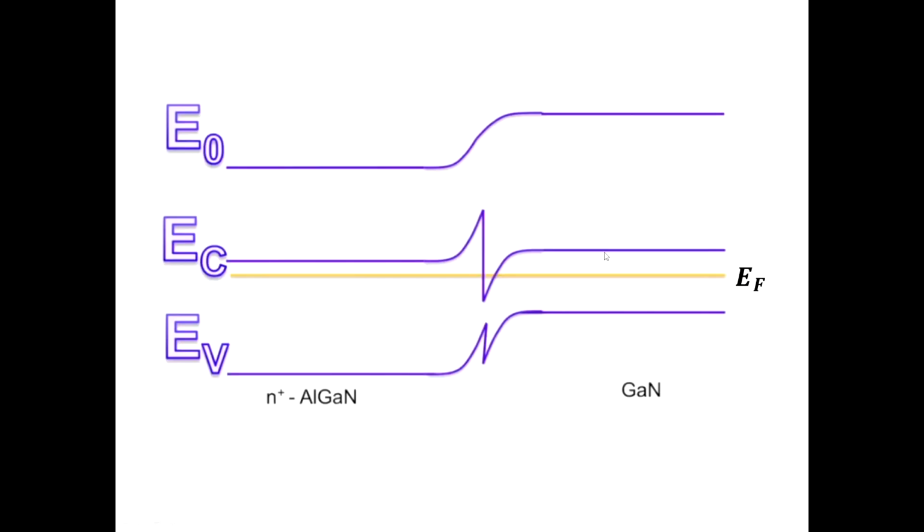So as a result, what happens? Normally it is the tendency of electrons to possess low energy. So electrons in this GaN layer fall in this trap. Electrons from the gallium nitride layer fall in this very small trap. So we get a huge number of electrons in this very small place. The concentration of electrons is very high here. From where are the electrons coming? They are coming from this gallium nitride layer.